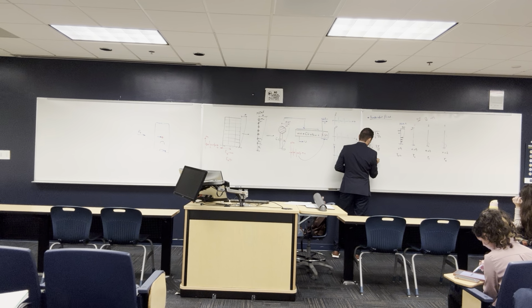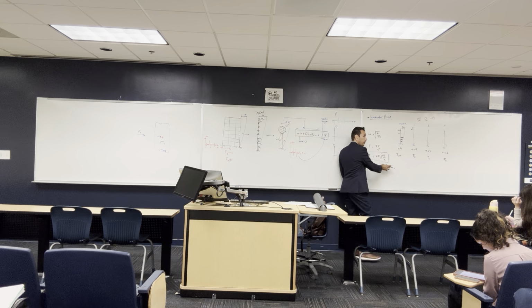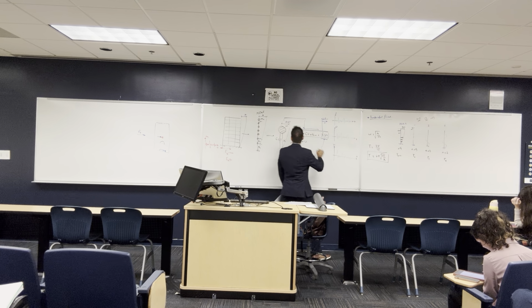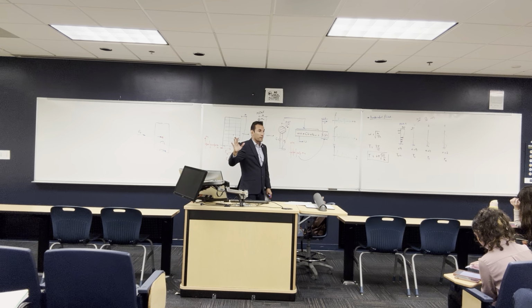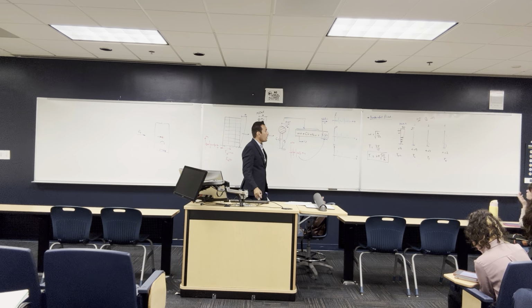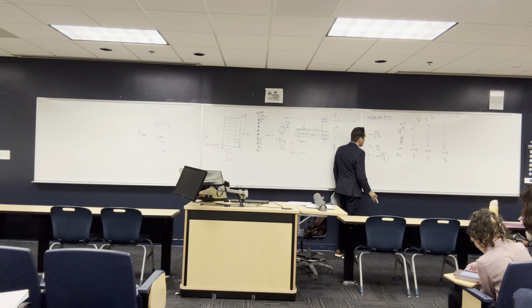So T is equal to 2 pi root the mass over the stiffness. That is the rule. If you know the mass of the building and the stiffness of the building, put them here. This is the total mass and the total stiffness after you do all the summation. So keep this rule in mind, okay?